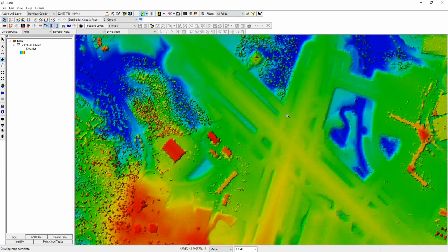Obviously, it's very important. It's a top-down 2D, planimetric view of your data. Very common way to look at your data. But there are other ways that we can look at the data, that we commonly want to be able to view our point cloud so that we can make assessments or do analysis on the point cloud. So the most common of these, of course, is a profile or a cross-section, a cut through the data so that we can see the vertical distribution of the points.